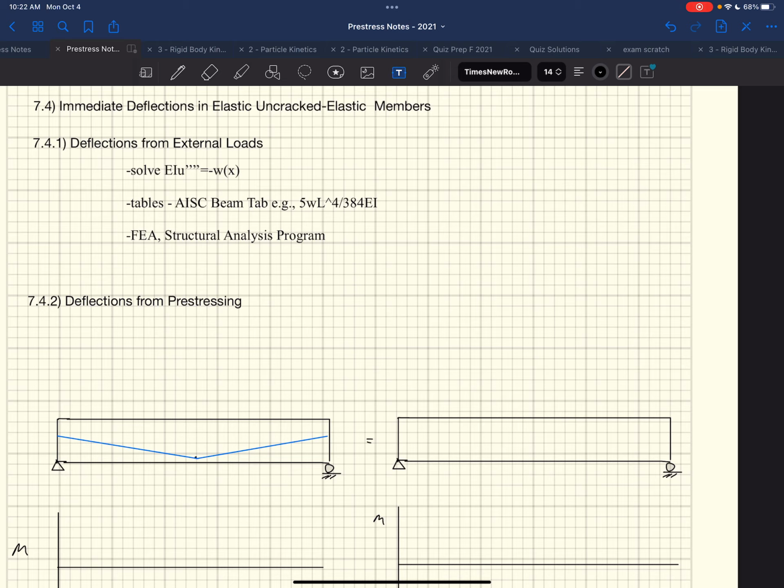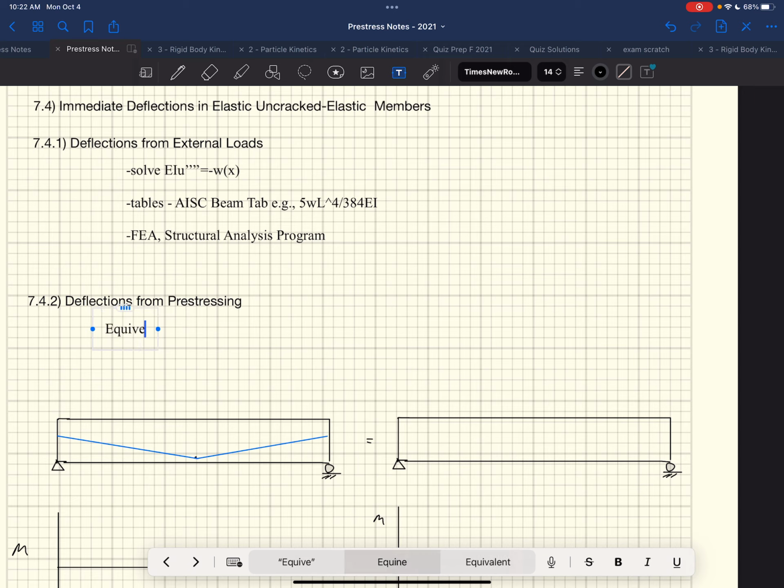This is kind of an equivalent force method, and I'd say this is part of it. We're going to find an equivalent force that does the same thing. This is going to be used when Kyle talks to us about post-tension floor design. It's all equivalent force method. You turn all of your internal stresses into internal forces, and then into external forces. You turn your internal stuff into external forces, and then you apply it to your structure and calculate. That's kind of what we do here. We ask what gives us the same moments and shears that this thing does. So, equivalent force method.